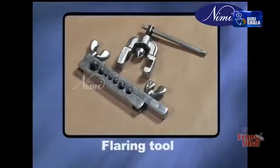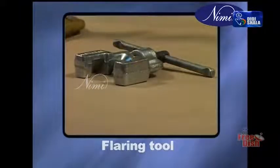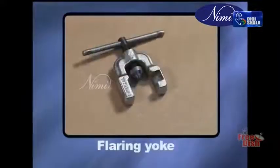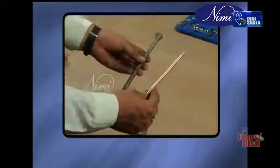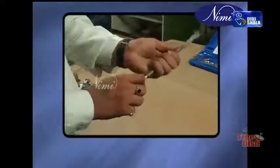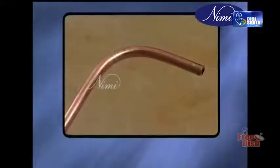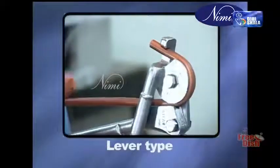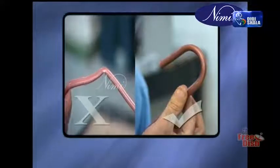Flaring tool. It is used for making up different types of flares of copper tubes. It has two parts: flaring bar, flaring yoke. Pipe bending tool, spring type. There are external coil spring bending tools where the external spring is designed to be used near the ends of tubes. Lever type. A lever type tube bender is used to form bends neatly and accurately without buckling the tubing.